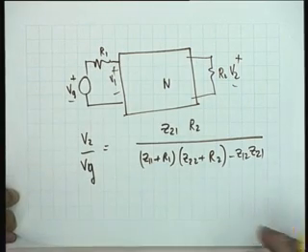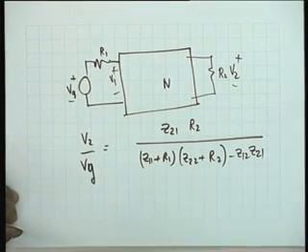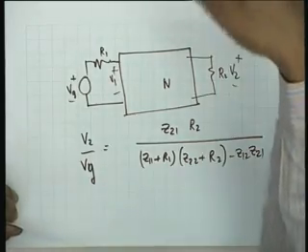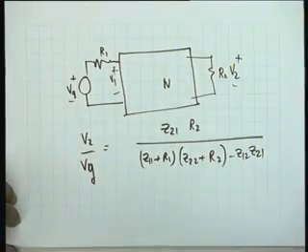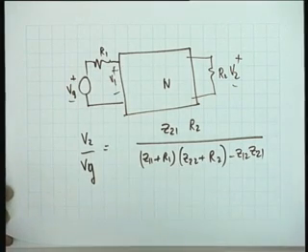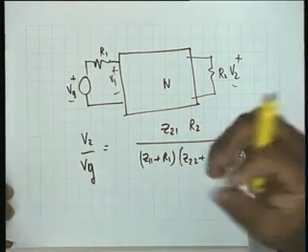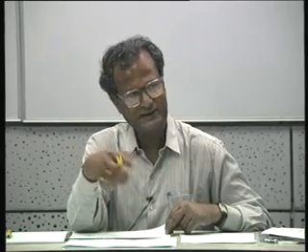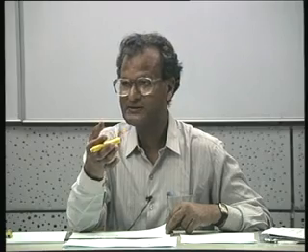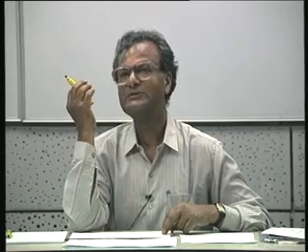The thing that I want you to notice is that in computing these simple transfer functions, we have always stuck to Z and Y parameters. And this is one of the philosophies of synthesis. Z and Y parameters came first into the picture. Scattering came much later. And the H parameters gained their prominence when the transistor was brought into the field of electrical engineering, so let's say around 1949 or 1950. The transmission parameters gained prominence when people wanted to build systems as a cascade. But basic transfer functions we work only in terms of Z and Y parameters due to historical reasons.